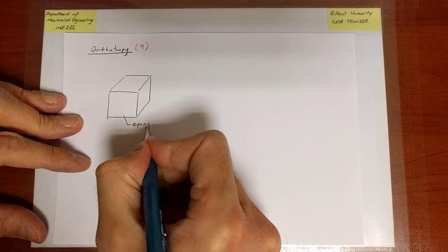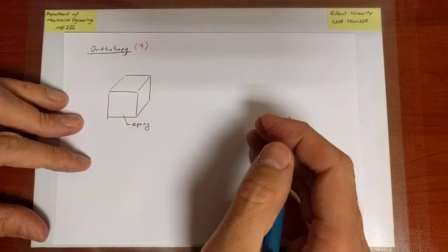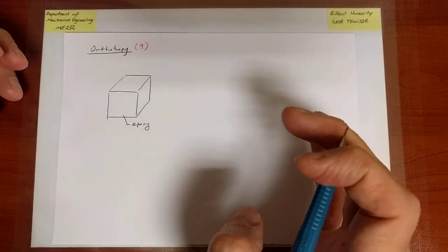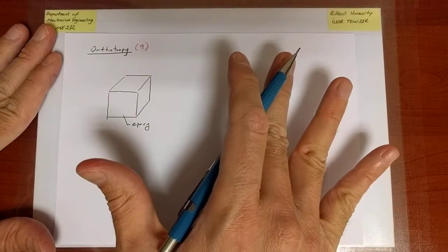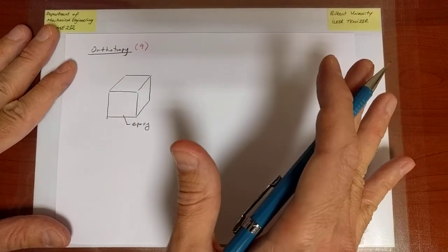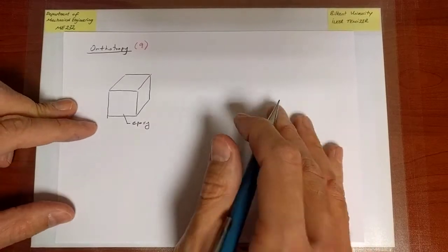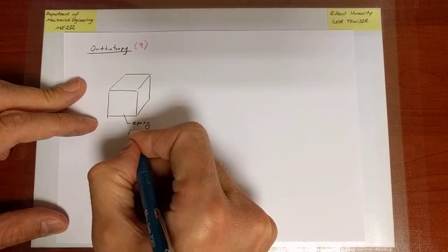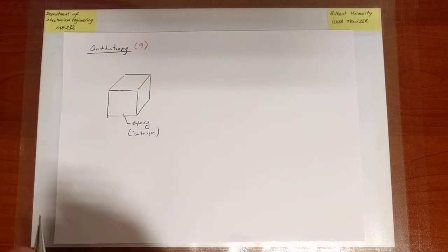It's a polymer. It's a thermosetting polymer. Thermosetting means when you heat it up, hence the name thermo, it sets. It retains a permanent shape. Initially it's soft. You can easily deform it into a shape you want, and then you bake it. You heat it. Making composites is like baking, and then it will retain that shape, and then you take that complicated shape and put it into a certain application. Epoxy is a polymer that is actually isotropic, before you do anything to it.